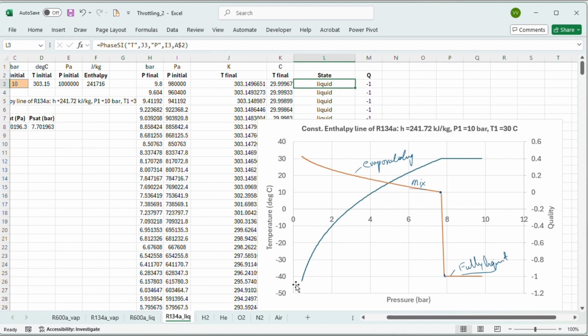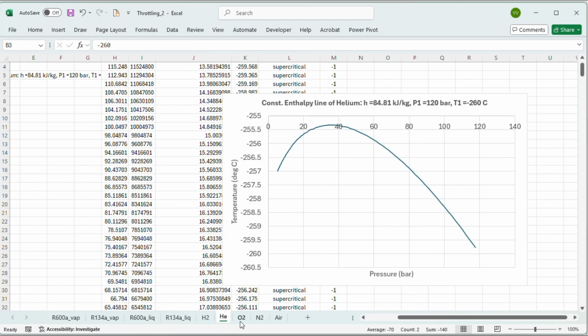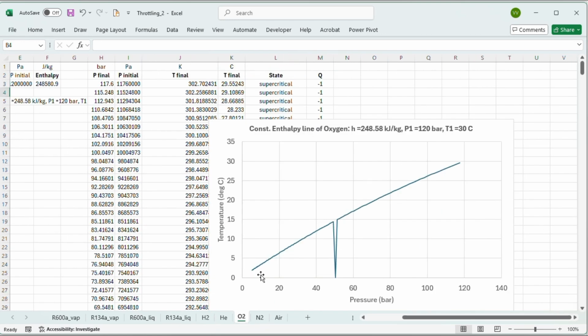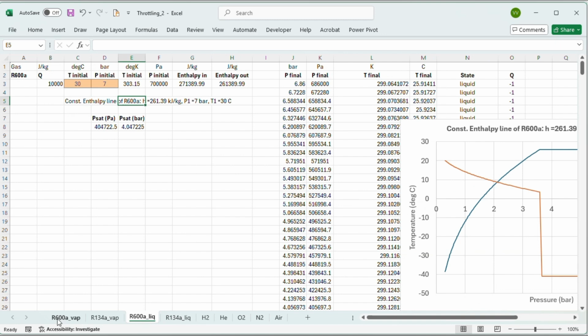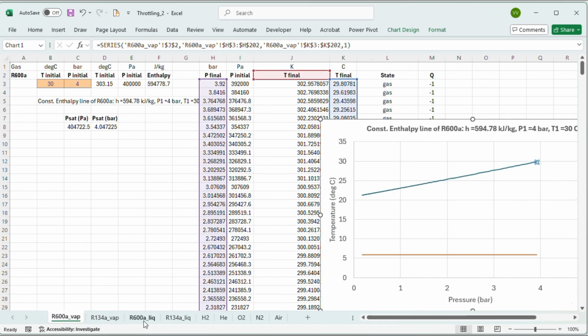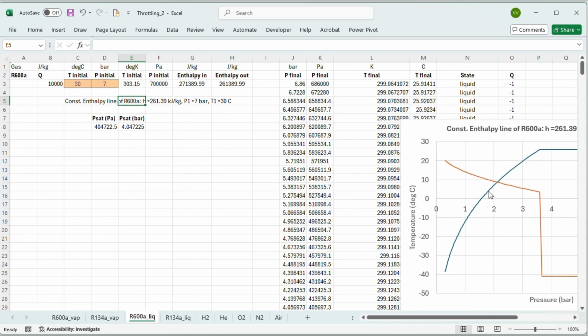That's where all the temperature drop happens, and it is a combination of the Joule-Thomson effect, which you saw here, where just the expansion drops the temperature of gas, plus it also includes phase change, which is why the drop in temperature is more significant when you have a two-phase fluid or a single-phase liquid going into the expansion device.